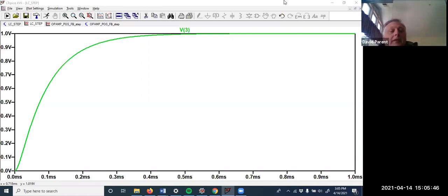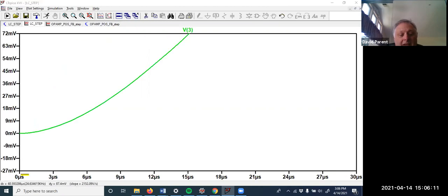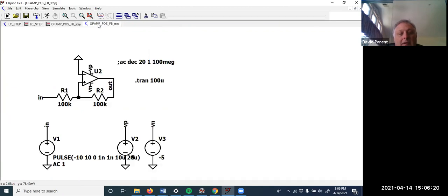Okay, so the thing is, second order circuits can be over, under, or critically damped. So just because there's no oscillations doesn't mean that it's not second order. It's a little bit tricky because it looks very close to a first order, and the only way you can tell is right here where you're getting this kind of shape, where a first order would just come straight up.